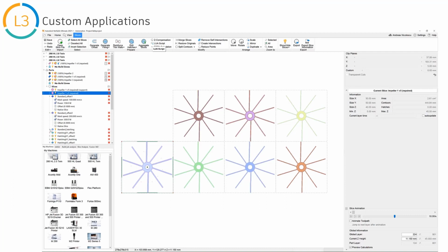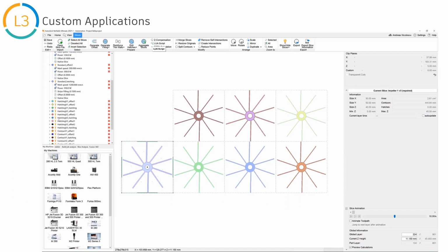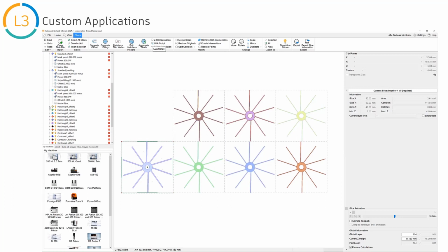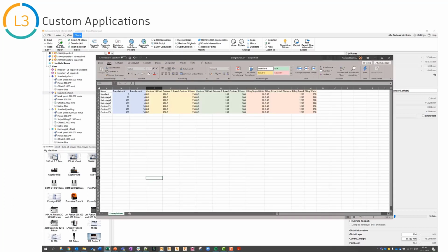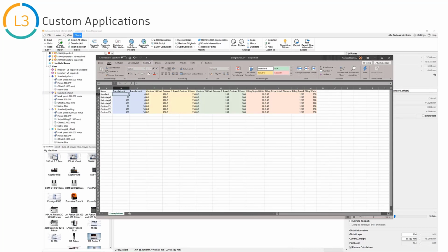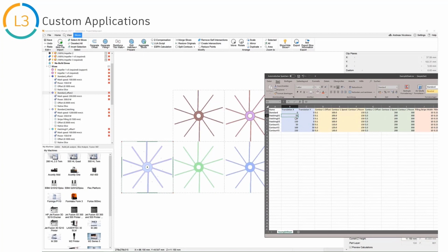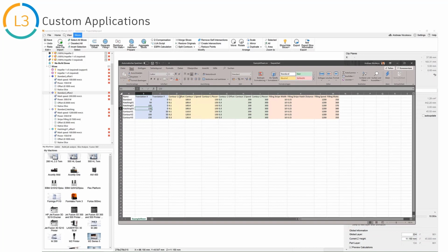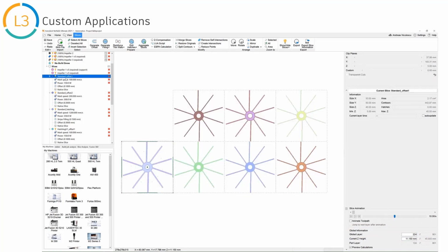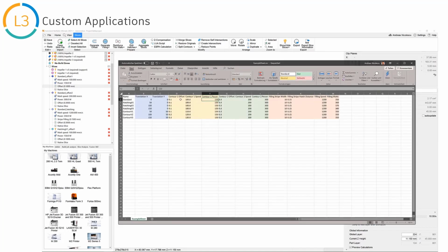What basically happened is that the script created a parameter study. The CSV table that we supplied in the first step of the script execution serves as the input criteria for our parameter study. For each line in our file, the script creates a copy of the part and links it to the exposure parameters in the columns. So by that, we can easily and quickly set up a complex material study with many different iterations and combinations of parameters.